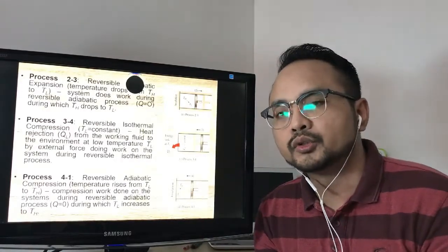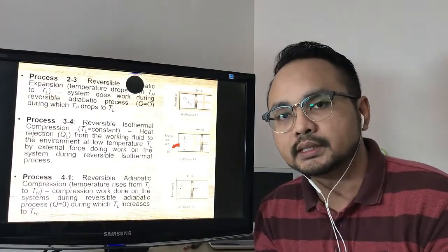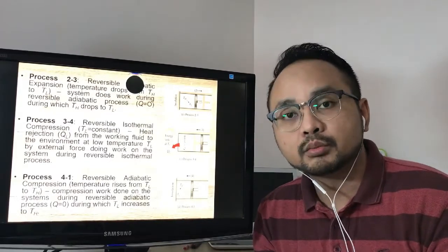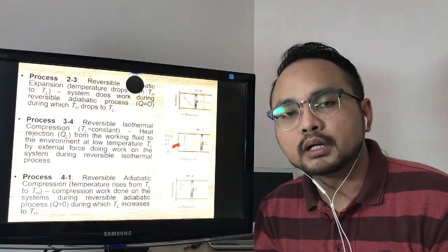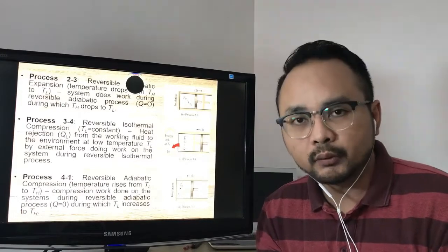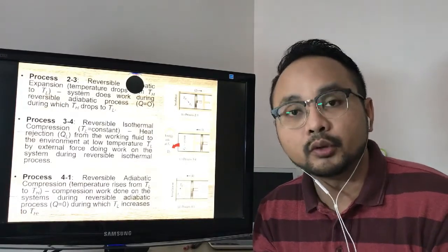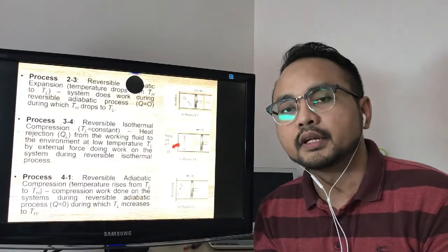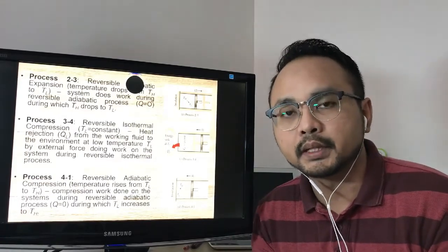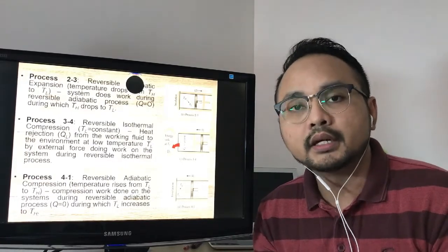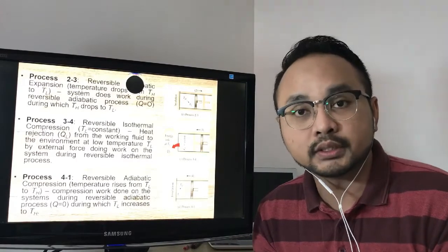From process 1 to 2, and it is going back to its initial state, we can see that it happens smoothly, and whatever work or heat transfer within the surrounding and the system, it will leave no trace. If heat is transferred into the piston cylinder in the first place, at the end of the day, the Q will be transferred out back to the surrounding.